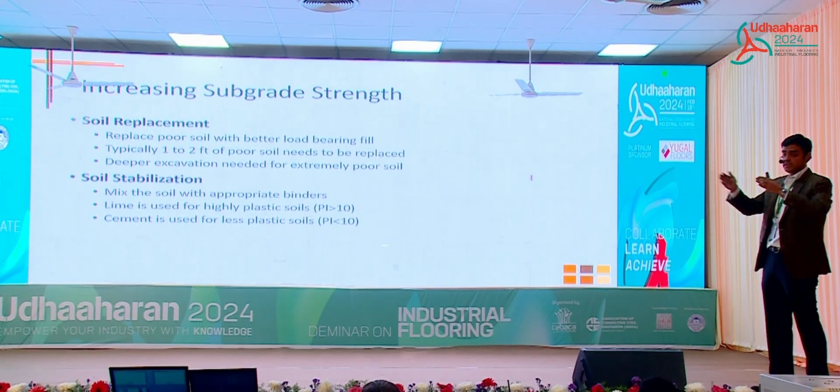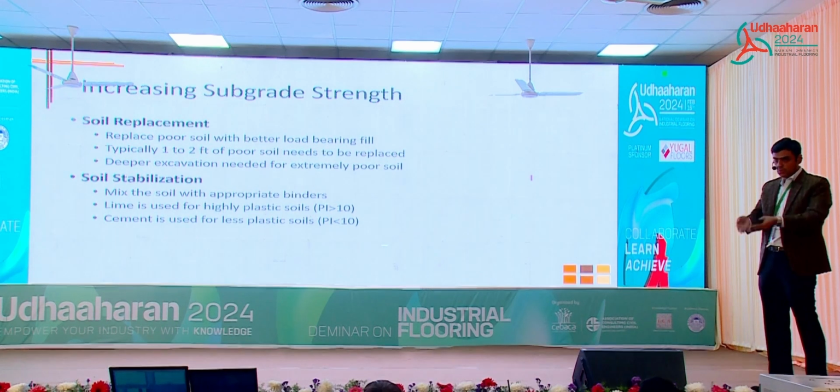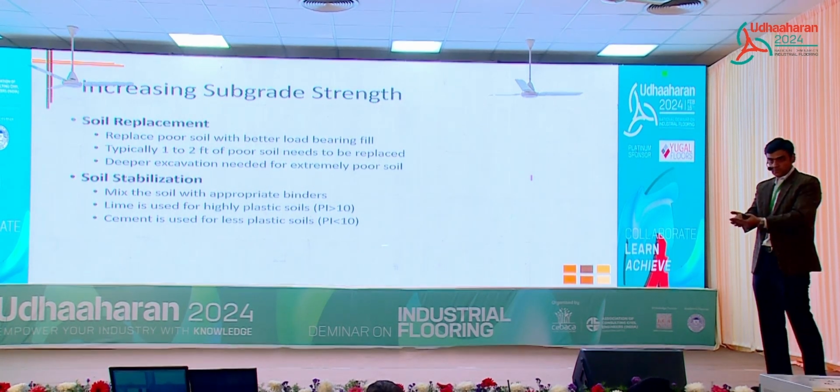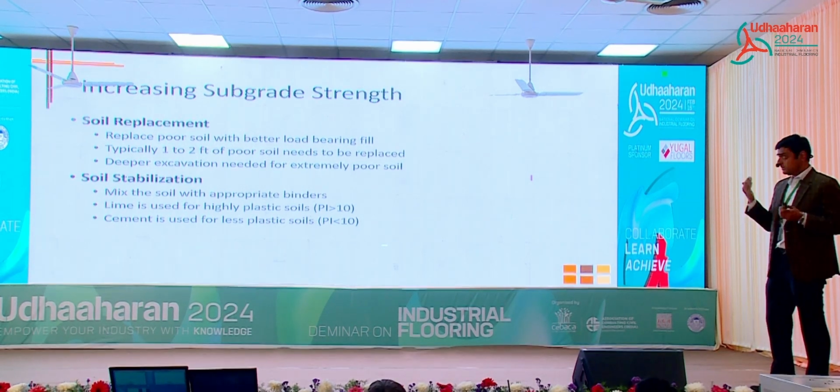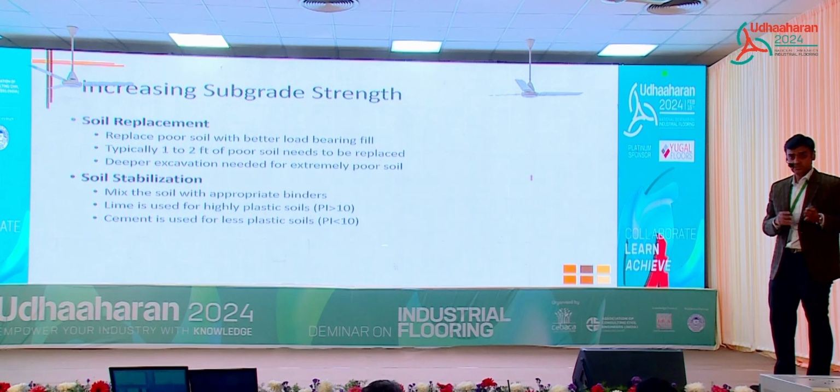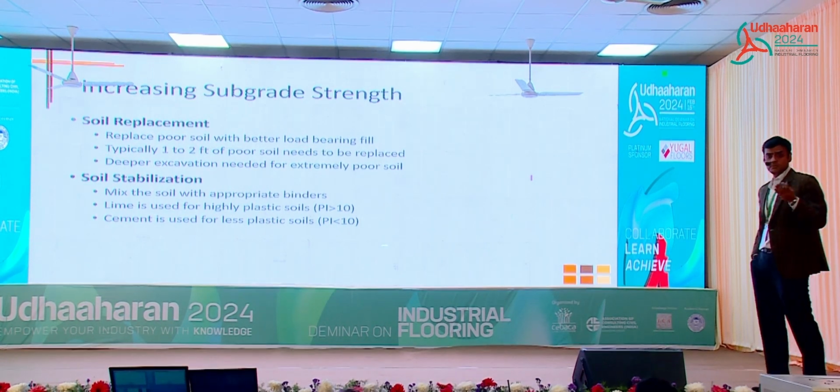Because again, as I said on the first slide, as you go lower, the load disperses, and you have lesser pressure or force on the poorer soil. If it is extremely poor, do a deep excavation. For soil stabilization, you could use lime, cement, or fly ash.